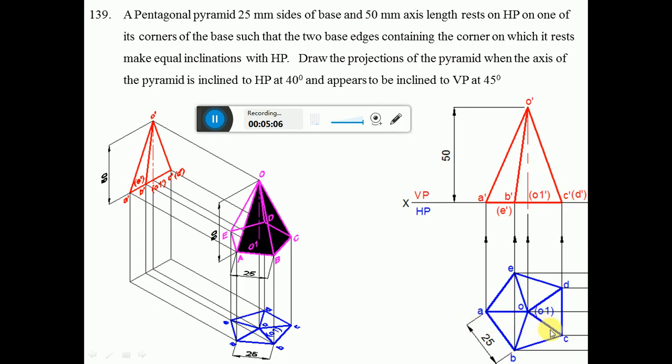To find the center, by using the protractor, you measure an angle of 54 degrees with respect to CD. Similarly, with D as center, you measure an angle of 54 degrees with respect to CD and then draw a line. These two lines will meet at this point, which will be called O. Then you join and dark OC and OD. Similarly, you dark OA, OB and OE.